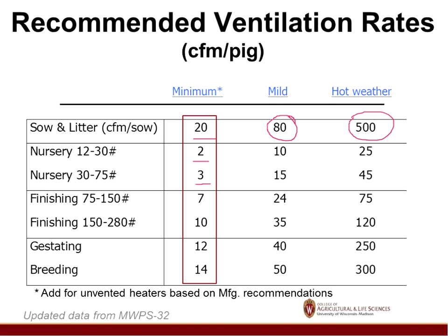But then when we get to mild or hot temperature, you're usually exhausting because of excess heat, not because of air quality. The other thing I might point out is swine and poultry use a lot of unvented heaters or direct vent heaters where there is no exhaust or a stack. All the products of combustion are dissipated in the barn. They require fresh air be brought in to maintain the oxygen levels. So that requirement, based on manufacturer's recommendations, has to be added to these.